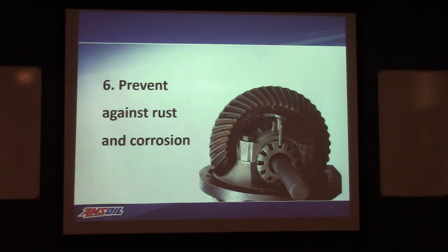Usually the oil is only there as a physical barrier, and is only allowing for short-term protection. If we want long-term protection, because that oil film is eventually going to wear off or run off, some other type of additive chemistry may be required.